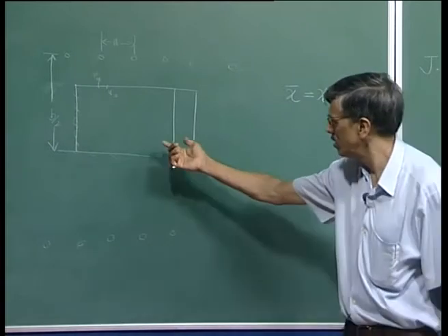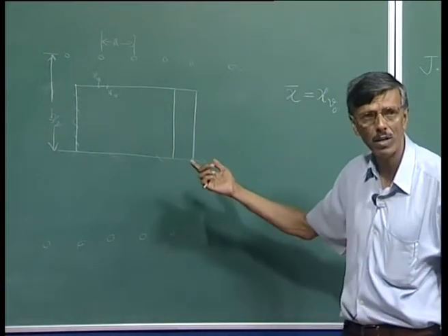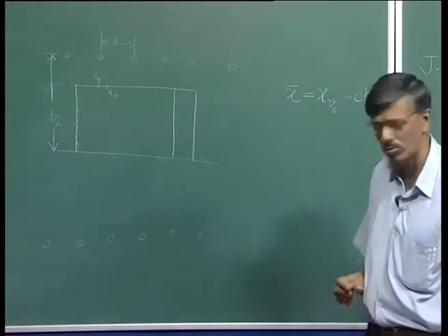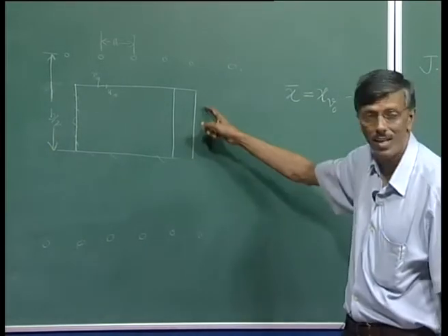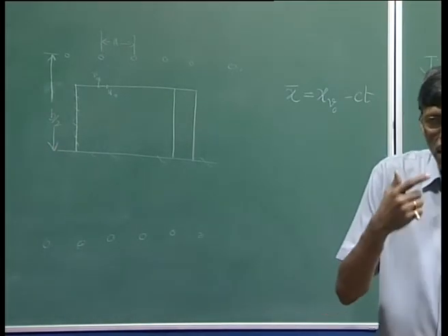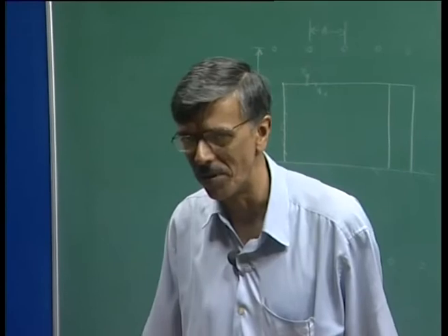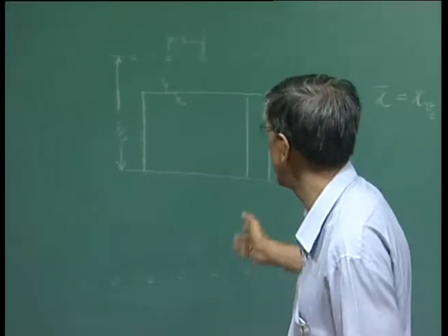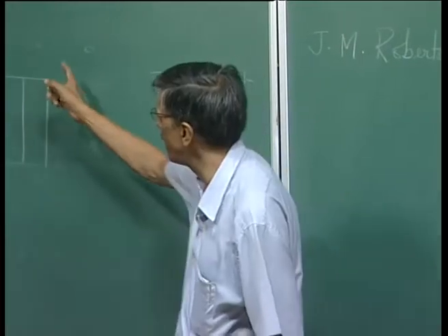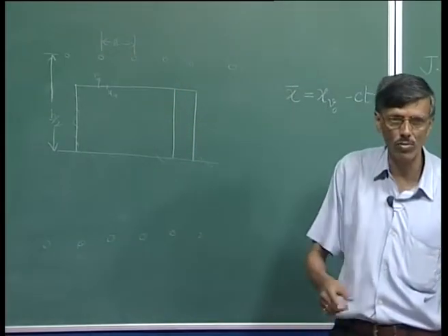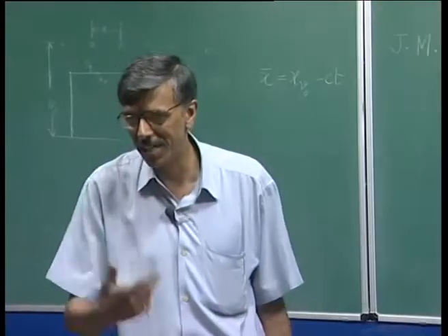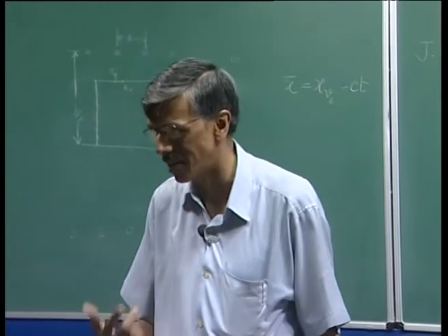They will amplify depending on the stability or instability of the problem, and they would like to go out. So here I don't want to a priori impose the condition that nothing has happened. We have to give some boundary conditions here which will be independent of what the inviscid flow is doing, because the dynamical system itself would evolve and create additional disturbances, right?